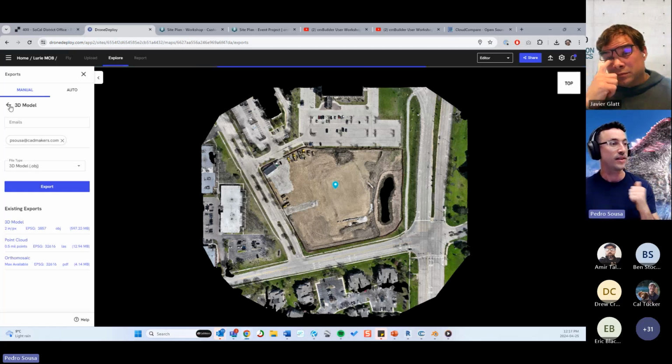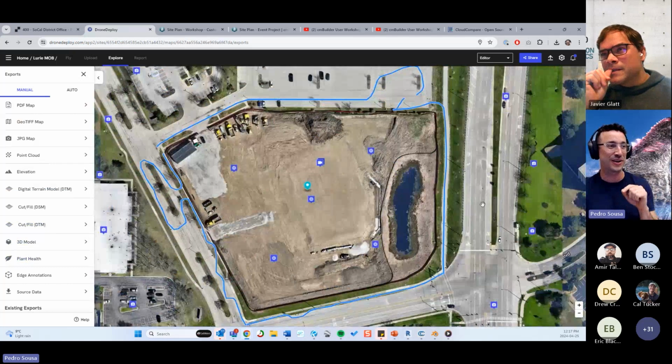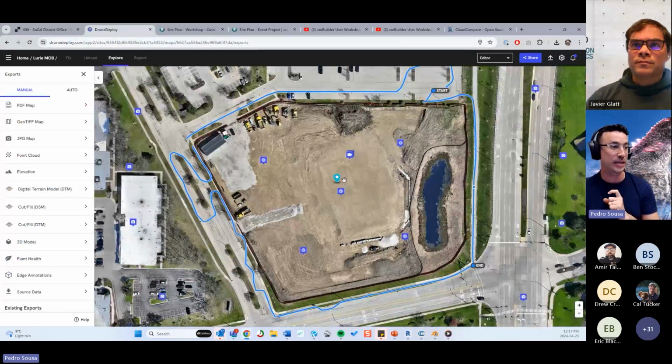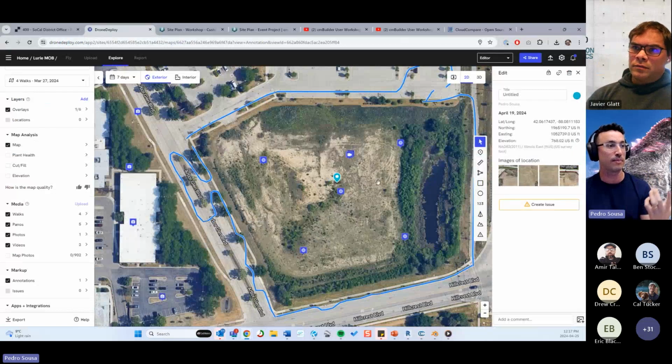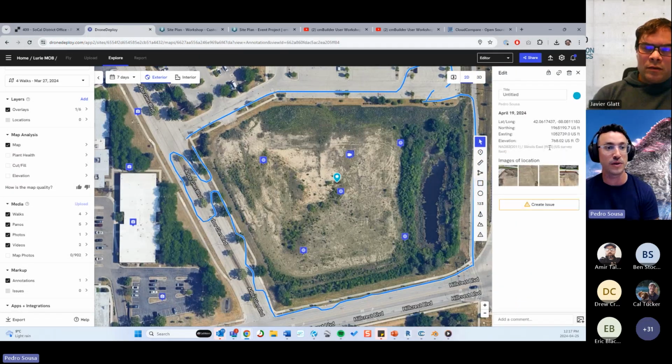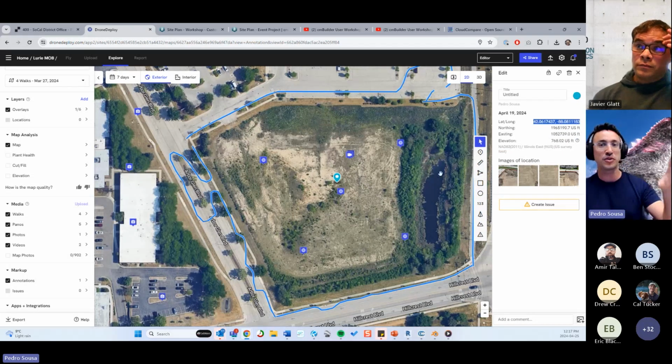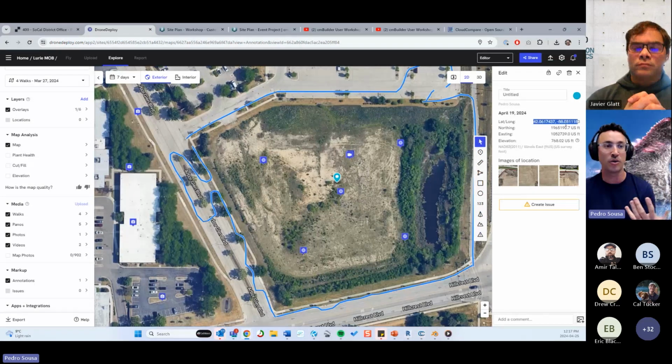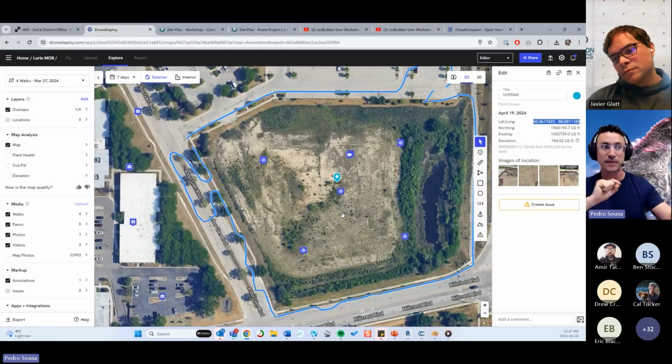One thing that I just found out while I was preparing for this call today about DroneDeploy is that you can create some points in DroneDeploy. You can place a point over here by using this point location. And when you place a point at a location, it will give you the elevation of that point along with the lat and long. It might be interesting for you to check this first, and then when you create your project in cmBuilder, you use the same lat and long to create that project, because then there will be an easier placement, because the origin point of your map and the origin point of this mesh and this surface will be the same, right? So that's a good thing to do.